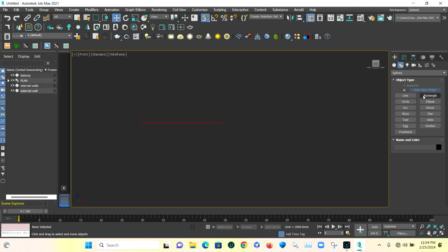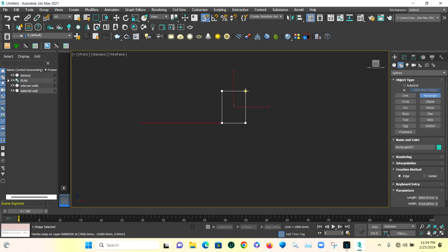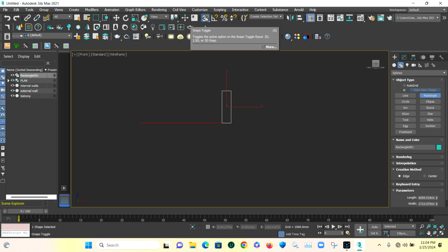So what will I use? I'll go to create. I use rectangle to identify my block heights. So I just create a rectangle irrespective of anything. Remember this toggle, remember when to put it on and when to put it off. If at any point the snap becomes a disturbance, you put it off. Now I can just put it off. I don't have any use of it now.